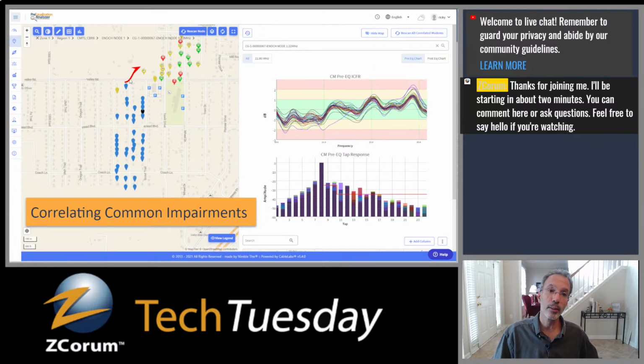And then you can look at it and go, okay, well, let's see. Let's say the outside plant distance that we're showing you is 334 feet. You can then look and say, wow, I've got a span of cable between this active and passive right here that's about that distance. And you can go look and check the connectors and whatever on that.